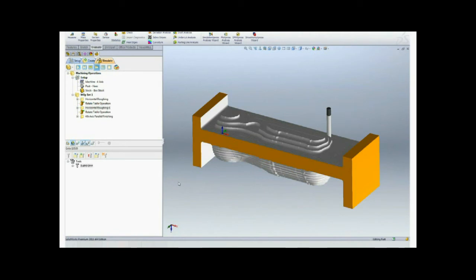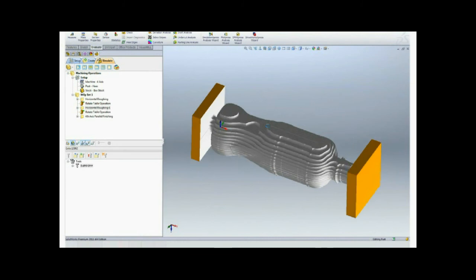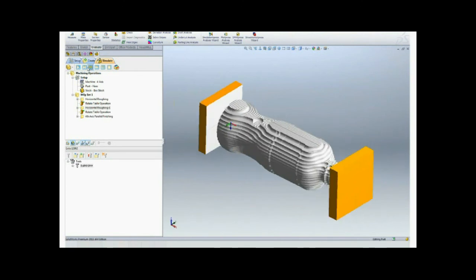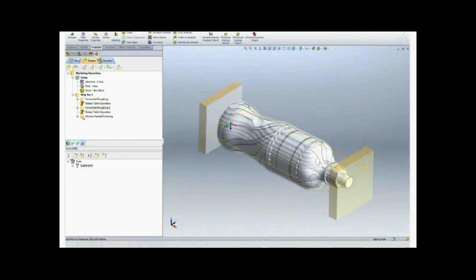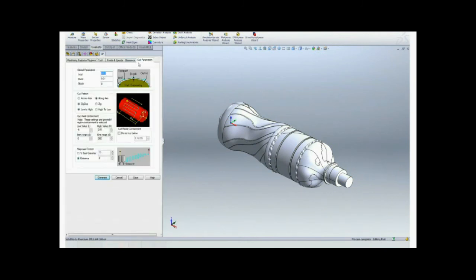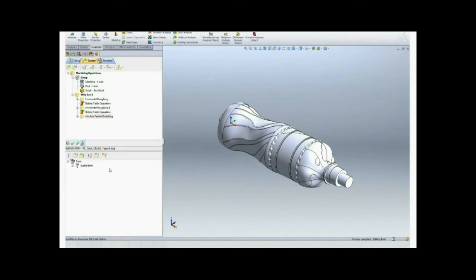The 4th-axis toolpaths can also be programmed by using a combination of indexed and continuous toolpath methods. So in order to create a finish operation, you would like to go back and apply a 4-axis continuous finishing operation. We will switch back to the Create Operations tab in the machining browser and apply a 4-axis finishing toolpath. The cut parameters can be defined to be either across or along the axis of rotation. The toolpaths can be contained axially by specifying low and high values and angular containments as well. And the user can also control the step distance for the step over.